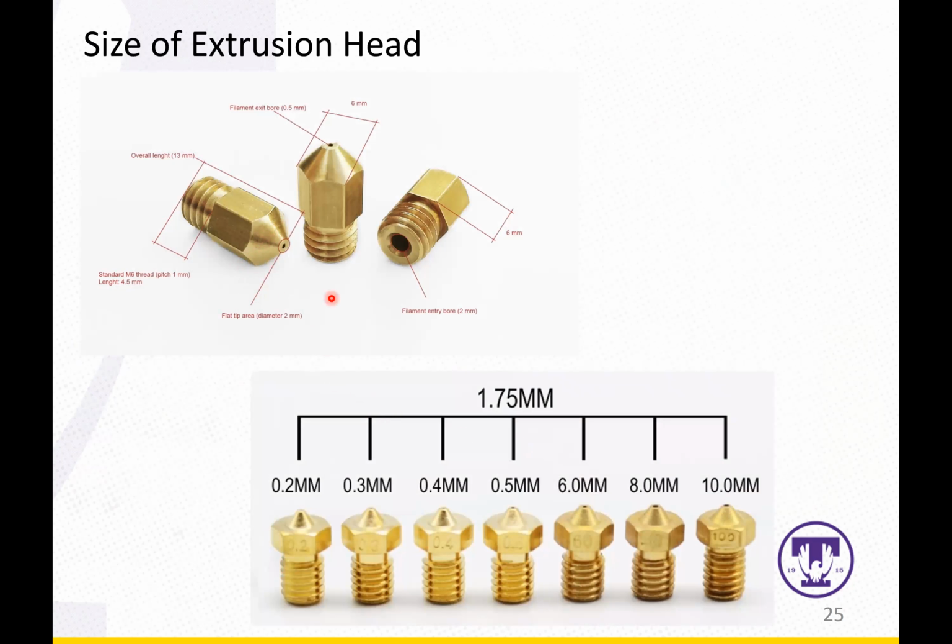I mean, for the length, I would say it's quite standard, but the most customized part will be the size of this nozzle head, right? It will affect the extrusion a lot, because the smaller size will give you less material extruded, and it will slow down the extrusion.